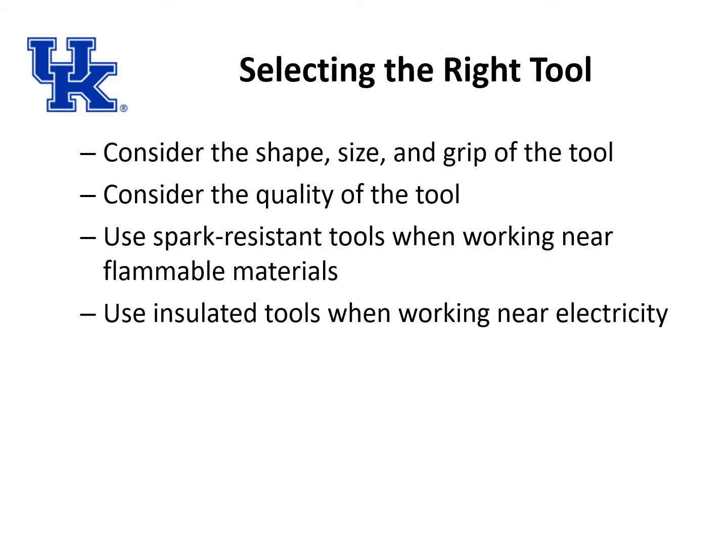When selecting the right tool, consider the shape and size of the tool and the grip of the tool. The handle or grip of the tool should be comfortable to hold and should fit your hand properly. Do not select undersized tools. Consider the quality of the tool. Cheaper tools are more likely to break, get damaged, or become dull. Select high quality tools. Iron and steel hand tools can generate sparks, which are dangerous around flammable substances. Instead, use spark resistant tools made from brass, plastic, aluminum, or wood.